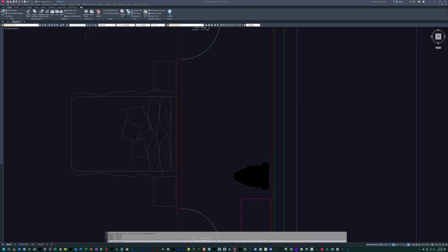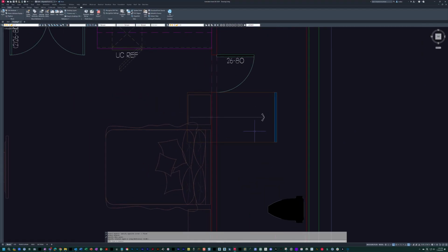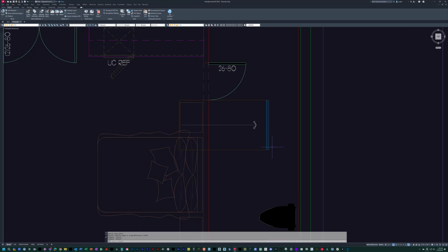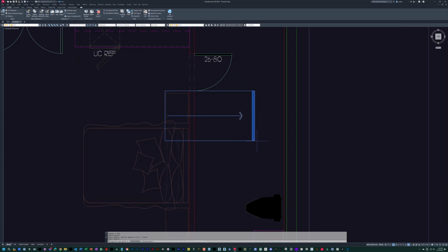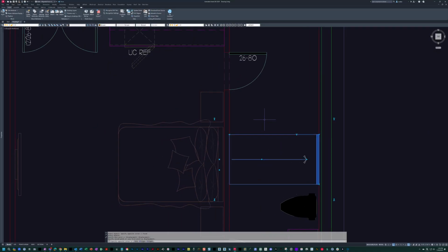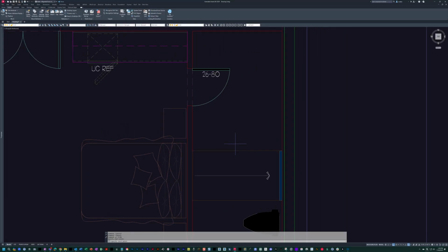From there, I can grab, again, some pre-made showers. I'm going to grab another block, and so this is my shower, and this is just going to be a linear drain. And I can grab and snap again to that node and place it right there. You can see we're already perfect width-wise. Let's see how deep this is. 3'4". It's a good number. 3 foot at a bare minimum, but 3'4" is not bad.